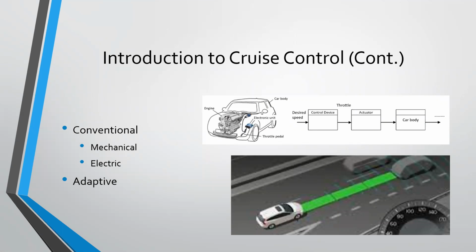A conventional cruise control system's primary function is to adjust the throttle input of the vehicle to maintain a preset speed. The vehicle's instantaneous speed is consistently changing due to multiple factors while driving. These factors can include dampening force from headwind against the vehicle, change in the grades of inclines and declines in the road, as well as a change in direction of the vehicle. Since there are multiple factors that can change the vehicle speed, the cruise control system falls under the class of a MIMO dynamic system. The term MIMO is the abbreviation meaning multiple inputs, multiple outputs.